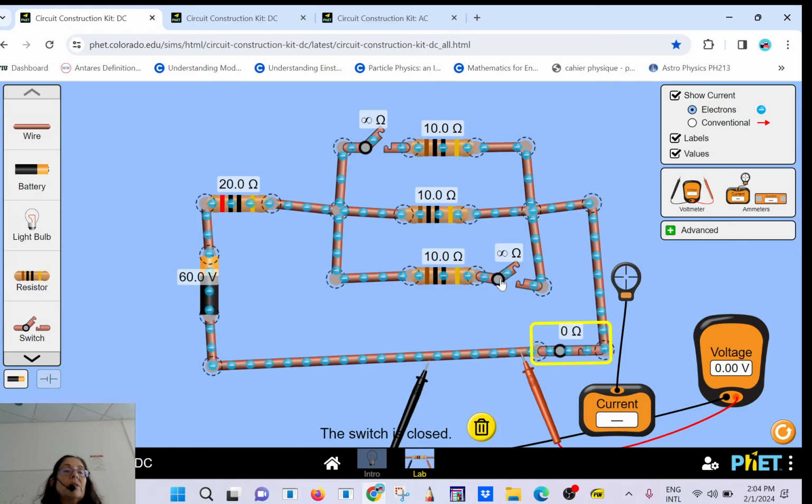So let me ask you the following question. If I close the switch here, and if I close the switch, so now what do we get? So I close the switch. Do you see it's flowing through here? You have an intersection, so you're going to have some current going here, some current going there, and some current going there. So this is a circuit in parallel. My question is, if you measure the current now drained from the power supply, is it going to be more than 2 or less than 2? Think about it.